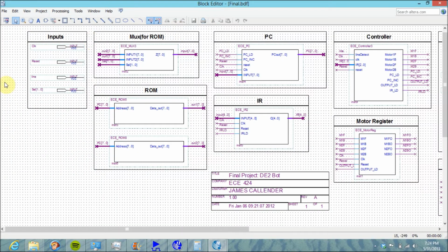to create its own window. So you can also notice that I'm using bus line, and this is this wire over here, orthogonal bus tool, and this will create a thicker line than what you would normally use, which is this line. So what this thick line is actually saying is that it's not only carrying one signal, it's carrying multiple signals, and the number of signals is specified by the labeling on that bus line.